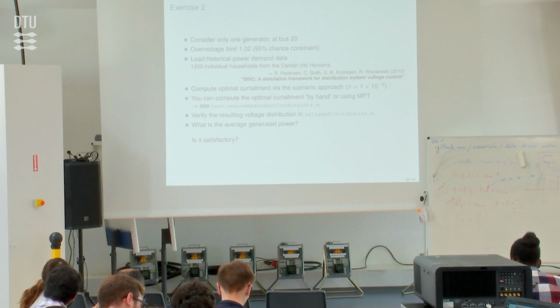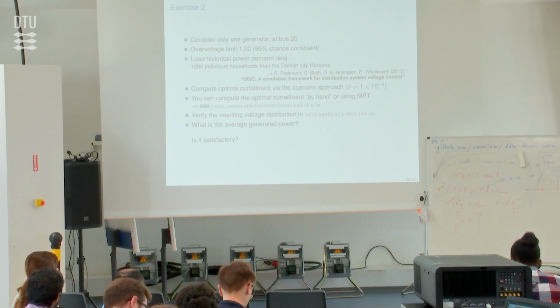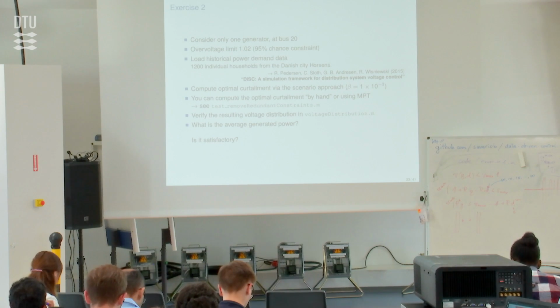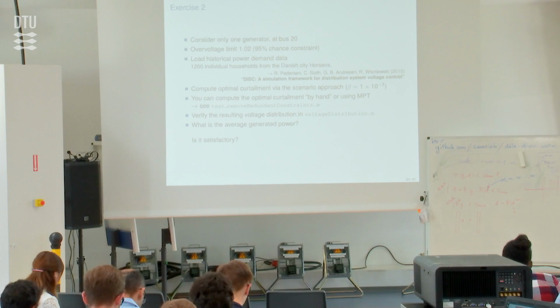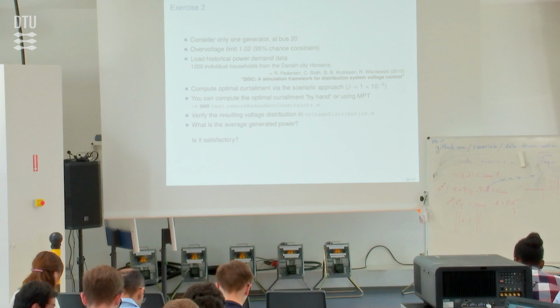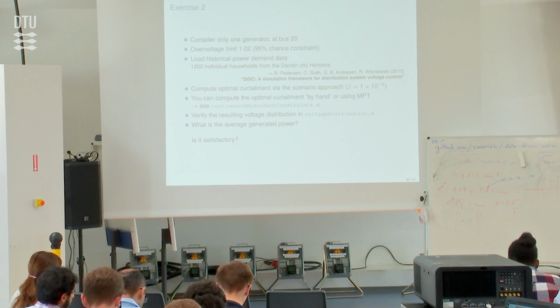So then we need to use this PF solution function, right? Not really. You just need to assume it's linear. You just use the capital N samples of the disturbance, and you assume that the problem needs to be satisfied for all those scenarios. Then it's basically that equation, Rg less or equal than Vmax minus 1 plus Rd, but you have capital N of these equations. So you have to stack all of them together, and then solve for G. Okay. Thanks. No problem.